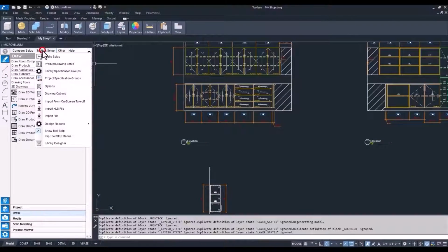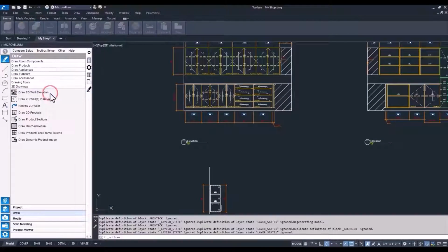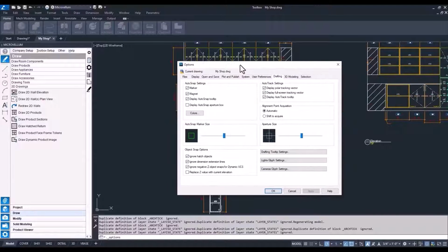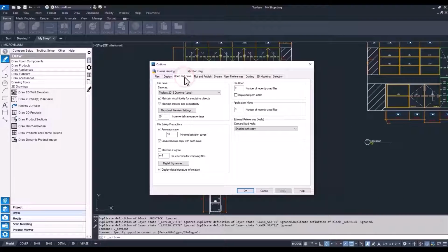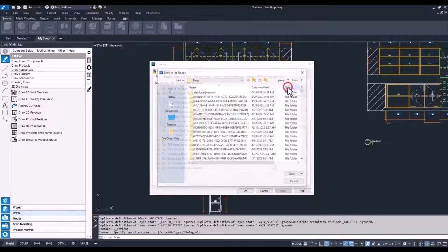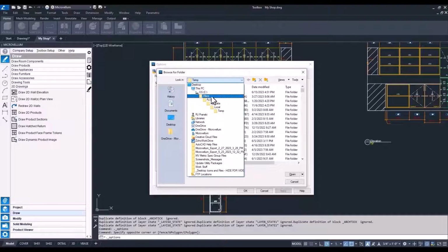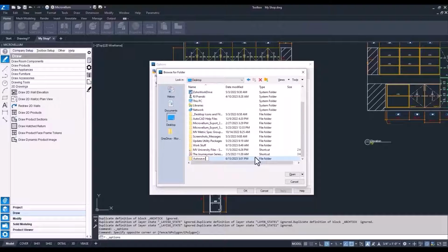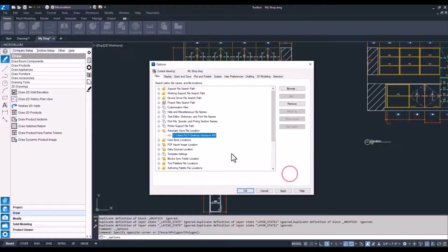So we're going to go into our drawing options. Then under the Open and Save tab, make sure you have that automatic save checked, and then however many minutes you want in between saves. And then now browsing to the location of where we want these drawing files to be saved in. I'm just going to put this one on my desktop, call it Autosave, MV. So now we have our new automatic save file location. Let me just be sure to hit OK.